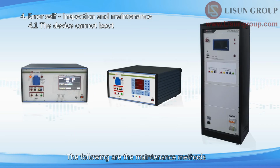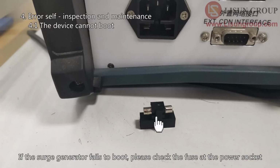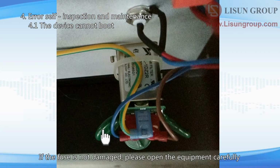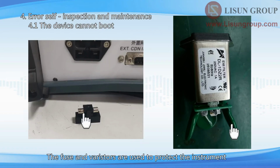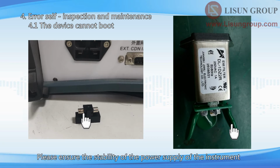The following are the maintenance methods. If the surge generator fails to boot, please check the fuse at the power socket. If the fuse is not damaged, please open the equipment carefully and check whether the varistors are burnt in the other side of the power socket. The fuse and varistors are used to protect the instrument. If there is a problem with the power supply, the fuse or the varistors may be burned. Please ensure the stability of the power supply of the instrument. If necessary, you can buy Builtin's regulated AC power supply.